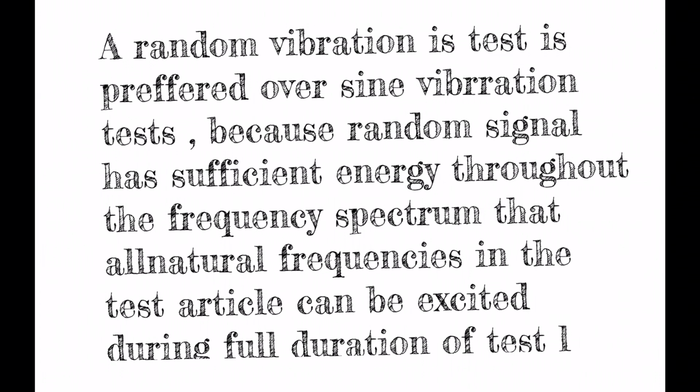One major reason why random vibration test is used as a screening test is that random vibration will provide energy to the system across all frequencies at the same time. So the interaction between multiple modes and everything can be clearly brought out in a random test, unlike a sine vibration test. So to sum up, there is no equivalent sine test for a random vibration test wherein the damage potential of both tests will be the same.